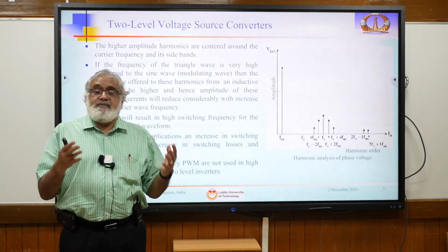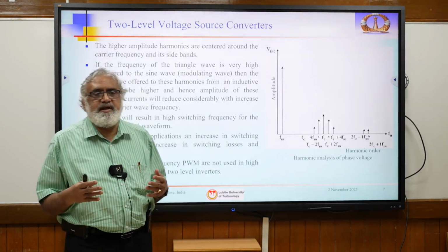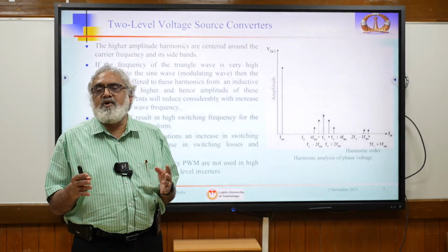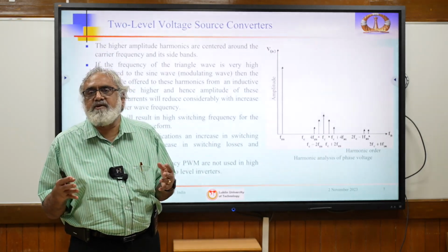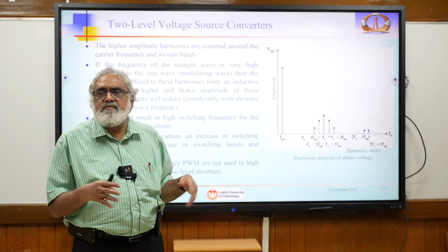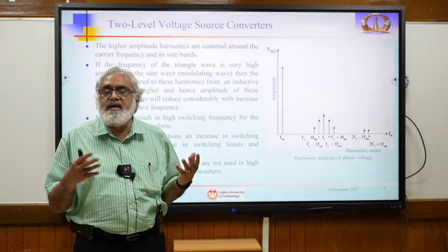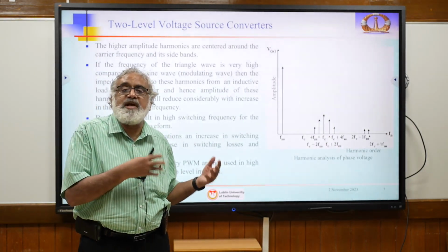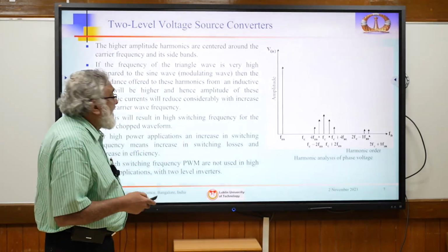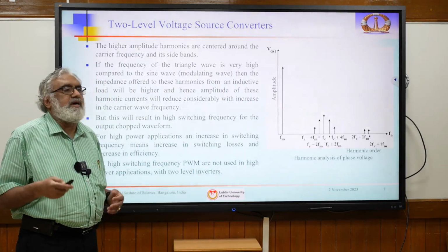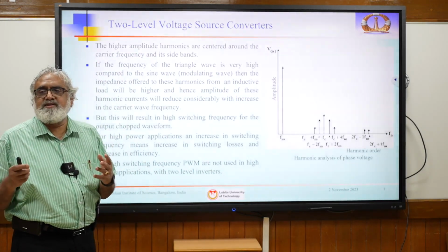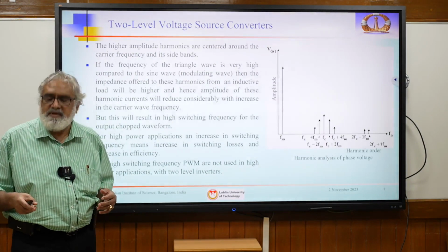At the same time, for high power, especially traction drives, we require a nearly sinusoidal voltage waveform. At the same time, we cannot resort to high frequency switching to increase the efficiency, because we would be switching high voltage and high current there. There the concept came: people thought about how it is possible to get a nearly sinusoidal voltage waveform with a stepped waveform.